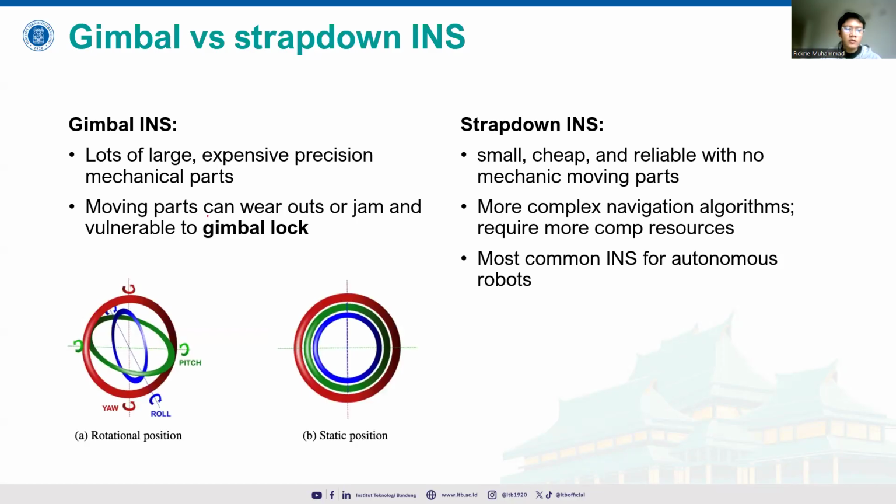So what is gimbal lock? If we go back to gimbal lock, the gimbal basically uses three rotational rings, or three nested rings, each of them capable of rotating around one axis: yaw, pitch, and roll, as you know. And when two axes align, the system can no longer distinguish certain rotations because it's losing the ability to track or control the motion in one direction.